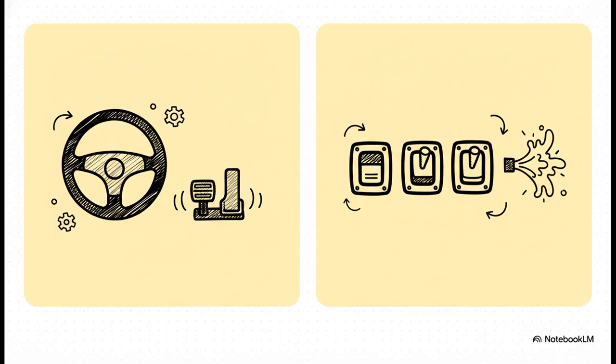On the other hand, M-code acts more like the switches on your dashboard. It controls non-geometrical or machine functions. M-codes are what turn the spinning spindle on or off, tell the machine to change the tool, or spray coolant to keep the metal from overheating. Working together, G and M codes conduct the entire mechanical symphony.